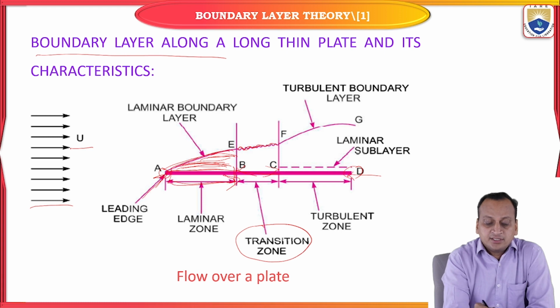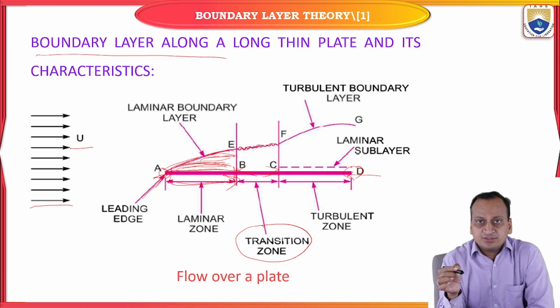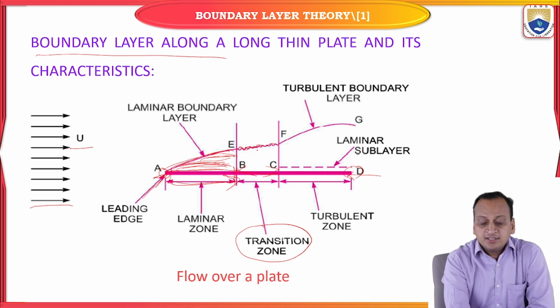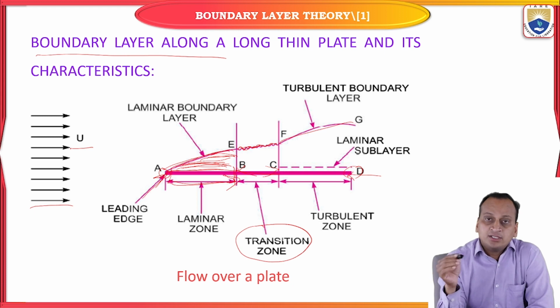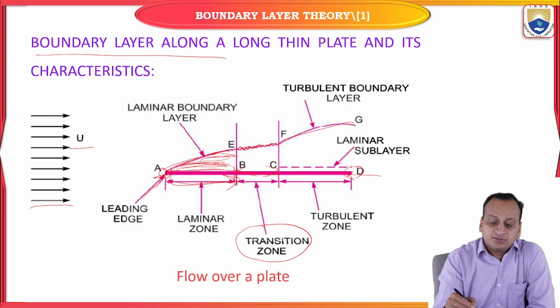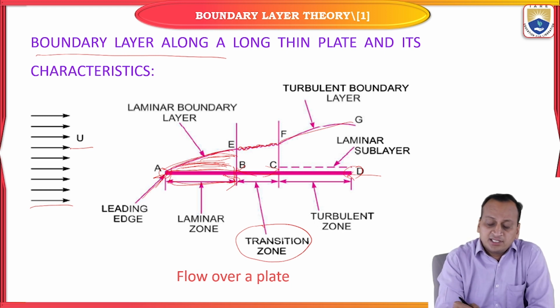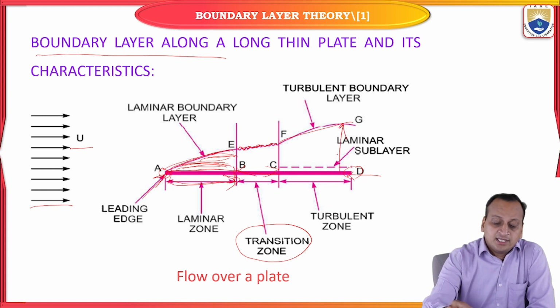After that, the fluid flow gradually increases, and its velocity is going to increase. It is no longer completely laminar or a transition one, but it attains purely the characteristics similar to the turbulent pattern of flow. In turbulent flow, due to the increase in velocity, the boundary layer thickness also increases rapidly.